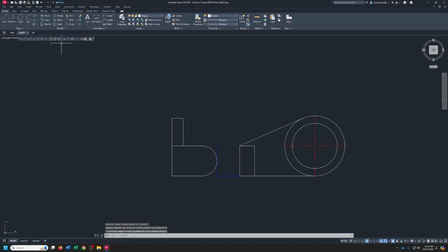And we got a little 1 inch circle in there, so I'll go back to diameter, pick the middle, and 1. Now we can get our hidden lines for this, right? I can go ahead and erase these 2 lines, we don't need them anymore. So I'll go ahead and switch over to hidden.